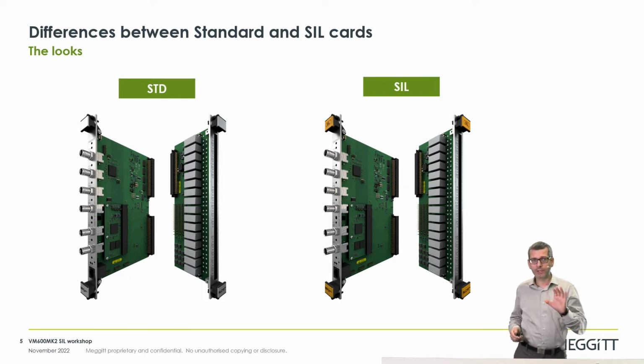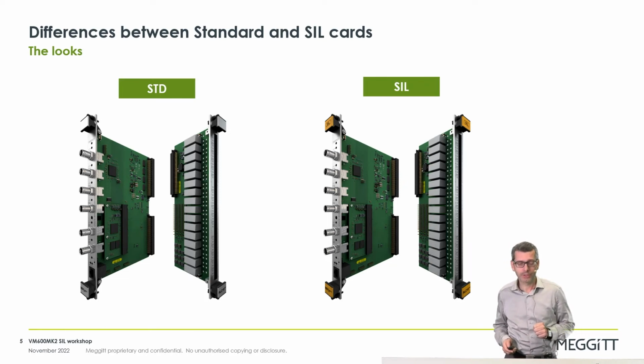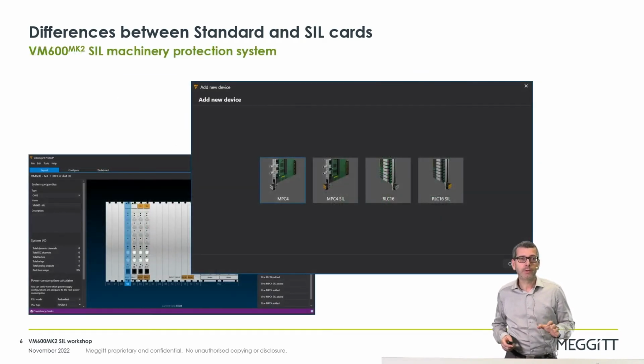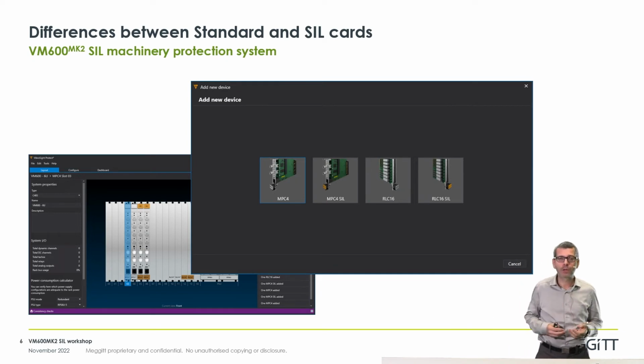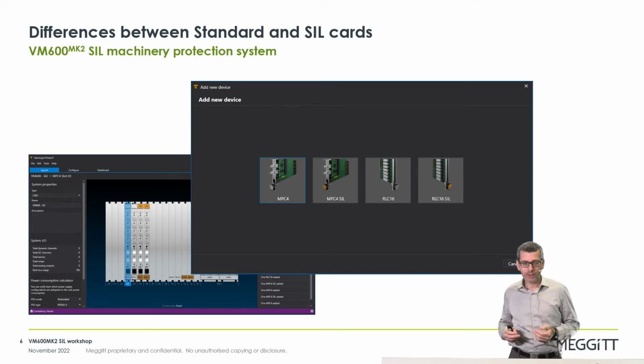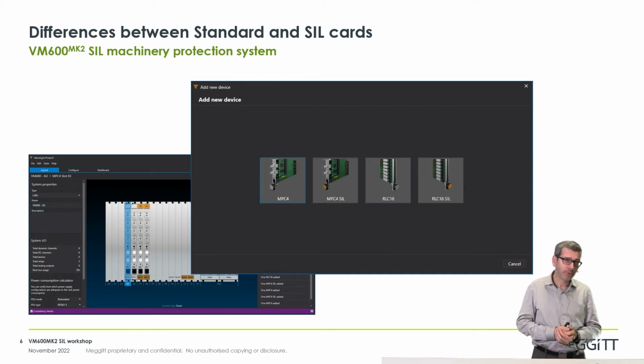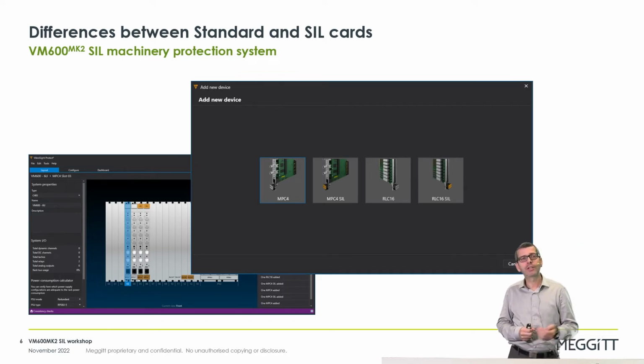Okay, so that's the first difference, which is a physical difference. Then, in terms of how we manage and configure these cards, there is not much difference between MPC4 standard and MPC4 SIL. We need to use vibro-meter protect software to configure the card, and vibro-meter system manager to set IP addresses, NTP server, upgrade firmware, etc.